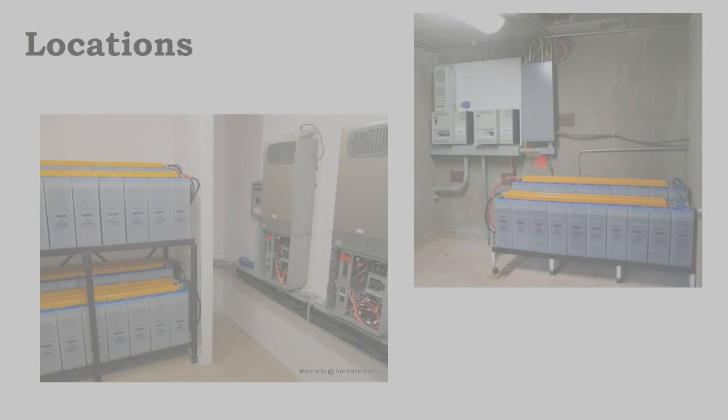So that is a code violation from clearance, and your batteries also need to be accessible for servicing. And so if this end of the battery bank needs to be serviced, and they have a watering system, they may only need to access this end of the battery bank, but accessibility of both ends of the battery bank may also be a concern.